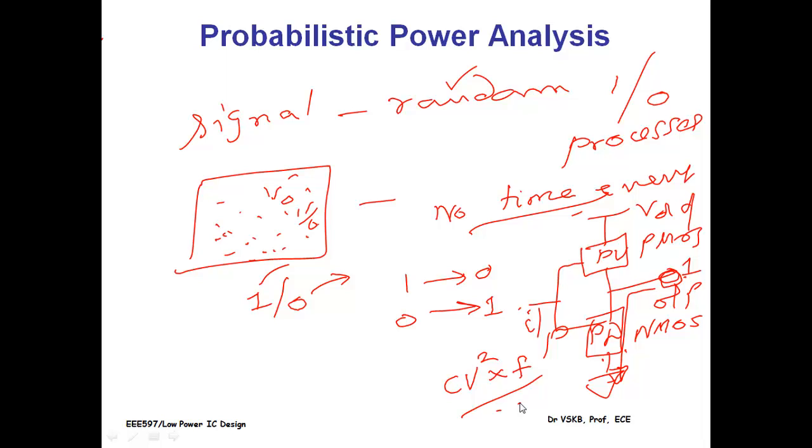And why don't I use this? Because I know in probability theory I am considering these nodes as having 1 which are becoming a 0, or some nodes at 0 which are going to become a 1, and all these transitions are literally helping me get the power dissipation measurement done. But I don't know particularly. I will give you a specific example later. Right now we will assume that every 1 to 0 or 0 to 1 transition makes some power dissipated in the circuit.